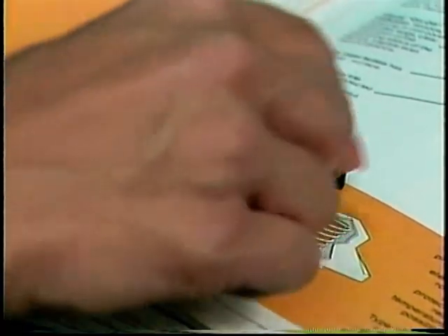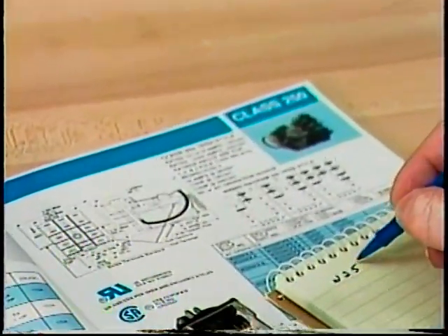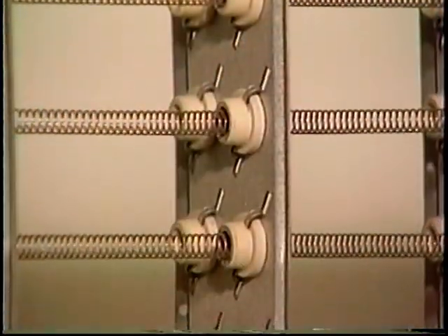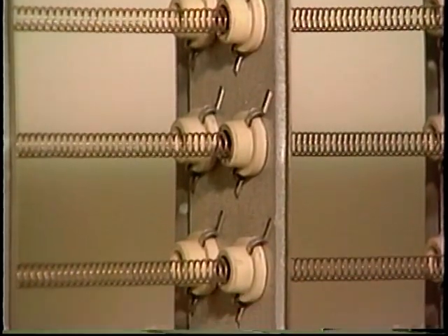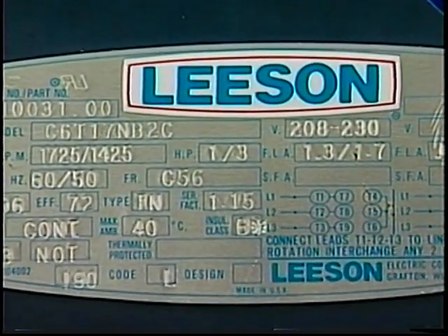The power formula is especially useful when determining expected current values, as most electrical equipment lists a voltage and power rating. The listed power rating is given in watts for heating elements and most appliances, or in horsepower for motors.